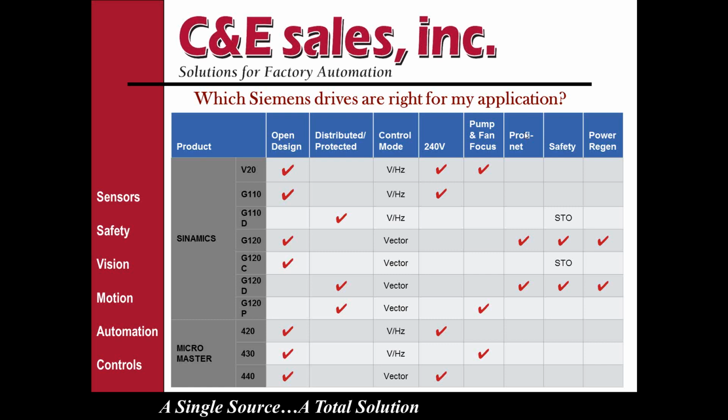Safety is another area that we want to stress. Most of the newer drives are available with safety integrated functions such as safe torque off and additional safety with speed monitoring. The advantage of that is that it integrates easily into your safety circuitry without the need for additional contactors or components. Not all of the Siemens drives have that capability, however, so you need to look at your application to see if that's a requirement.